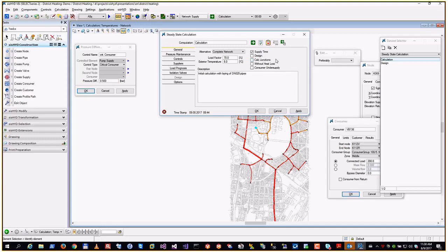At the very beginning, we discussed pressure loss computation in straight pipes. But in the connection point of pipes, depending on if they are in a very steep angle or in a flat angle, and depending on the flow direction, you can have pressure losses in junctions. There are formulas to compute it, and some of our users use these formulas.